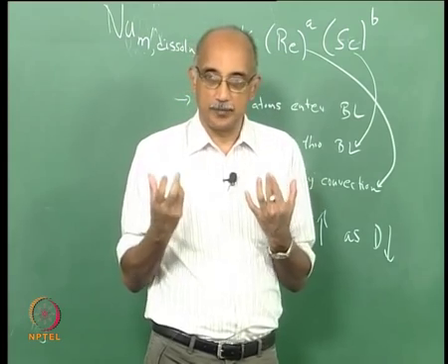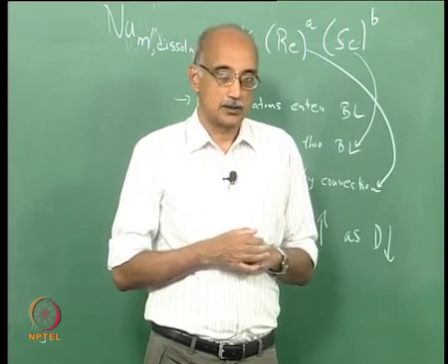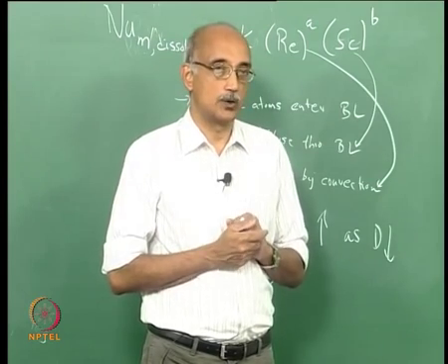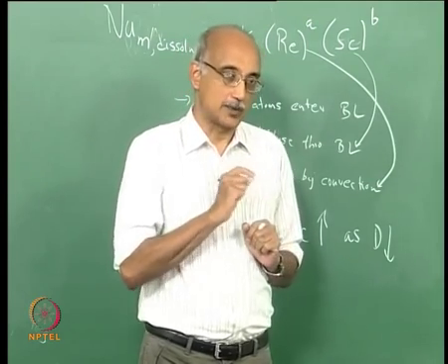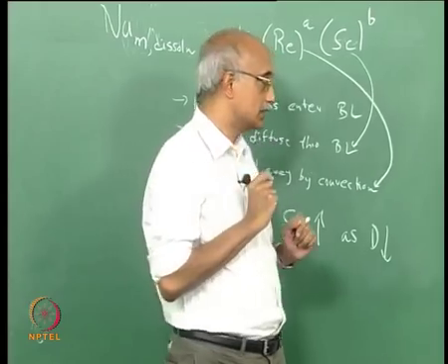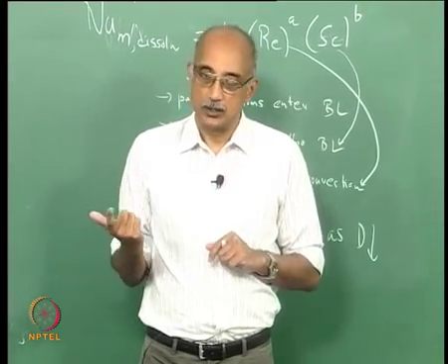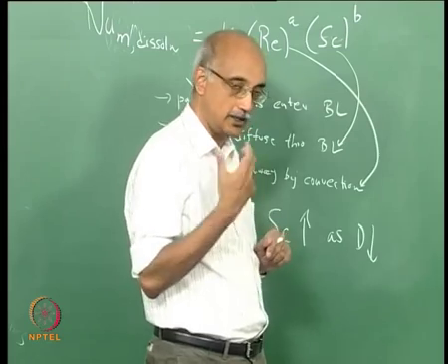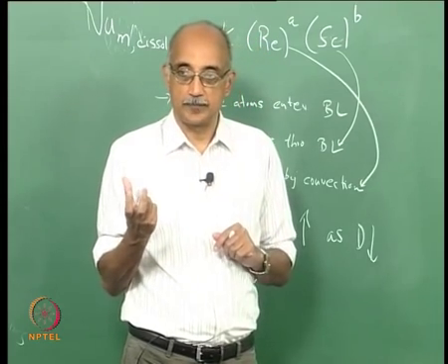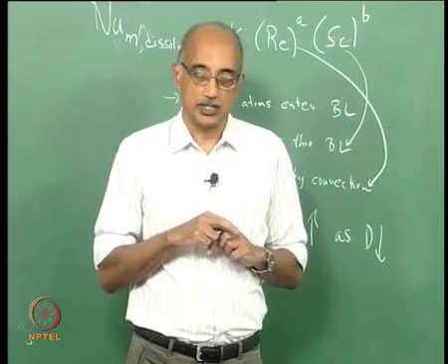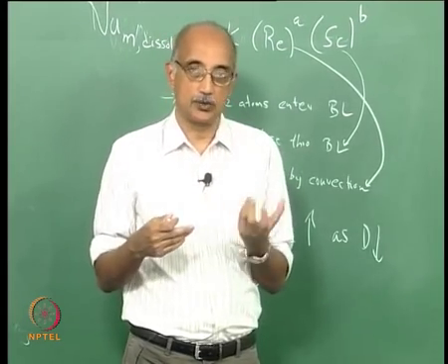What is the particle made of? And shape actually plays a less critical role in these particular aspects. In terms of the Nusselt numbers, for example, governing dissolution or sublimation, or even the kinetics of burning of a droplet, the shape of the particle or the droplet actually becomes a secondary factor compared to its size.